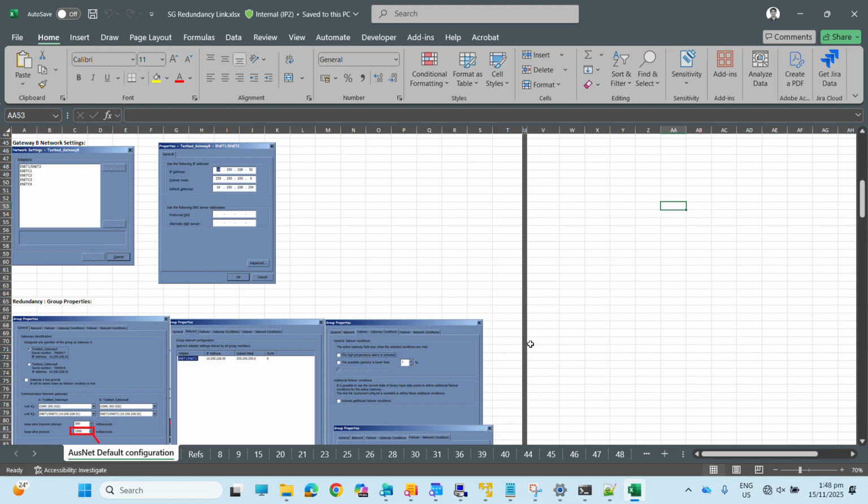Okay. And those switches, for both RTU. Suppose my RTU number 1 is connected with switch number 1. Is it mandatory to connect RTU 1 with switch number 2 also? Yes, it should. The two gateways should always be physically connected.